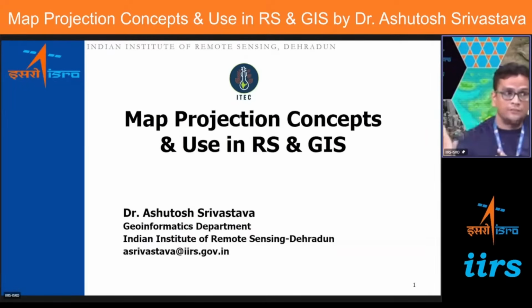The information from 100 years back will definitely be on paper sheets, and today's information may be satellite images. So the map that existed 100 years back, you have to digitize. After digitization, it will be raster data. When you bring raster data into GIS software like QGIS or ArcGIS, it will not have any projection system or coordinate system.